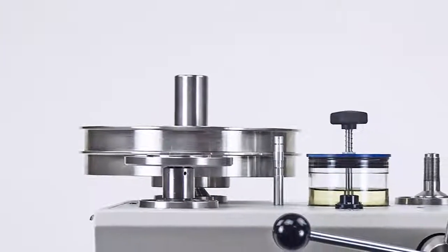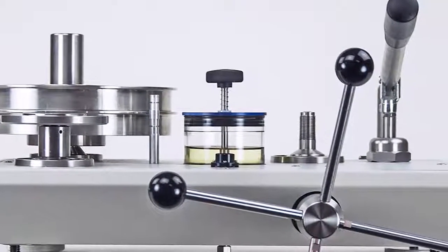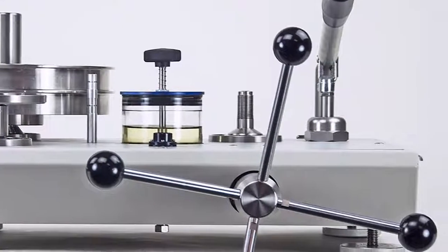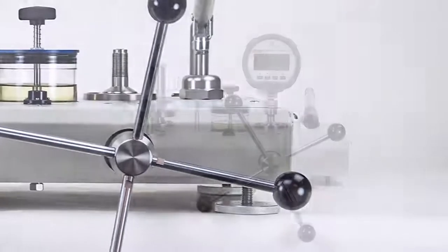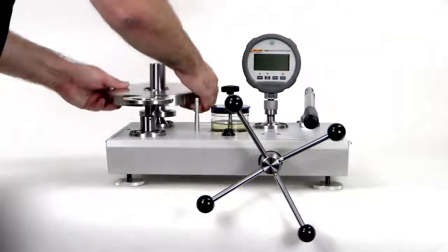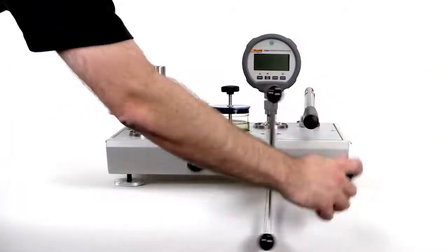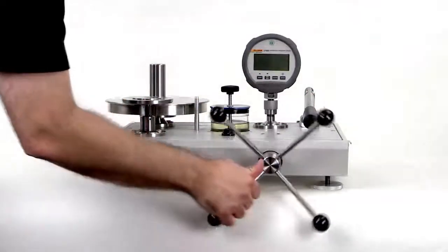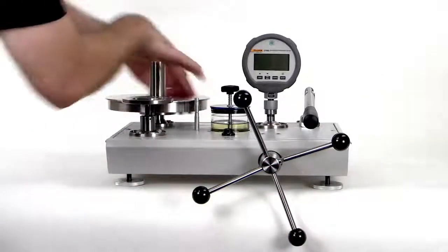Proper understanding of how a pressure balance determines pressure can ensure that it is used in such a way that is both sufficiently accurate as well as efficient. Depending upon the design, the physical operation of the unit can be relatively straightforward. You simply set the necessary mass on top of the piston and increase the pressure under the piston until it is floating.